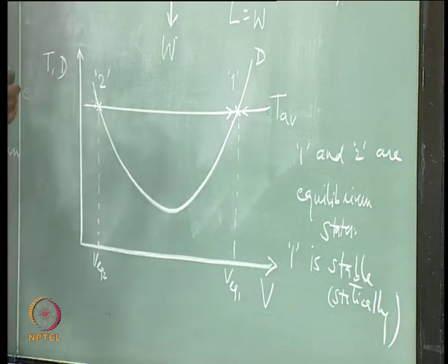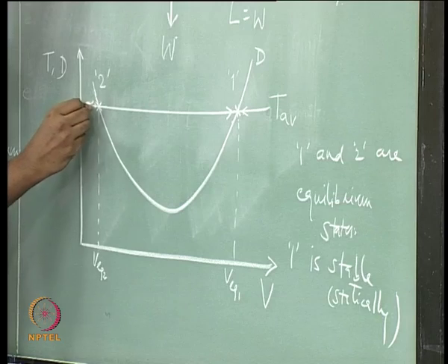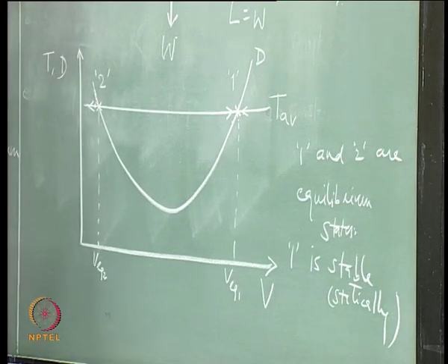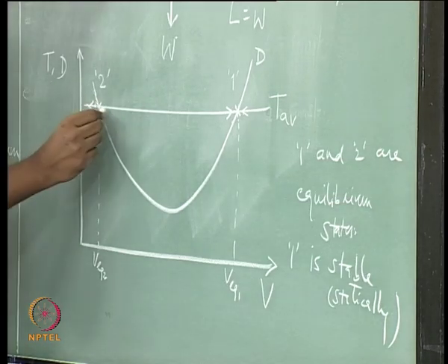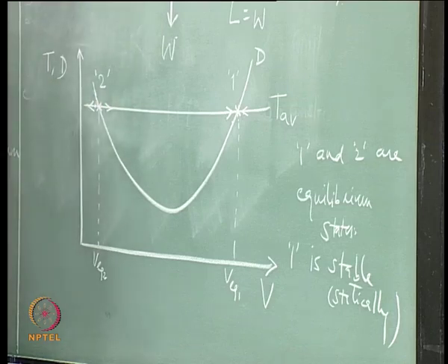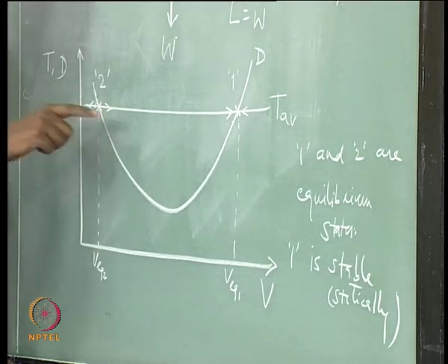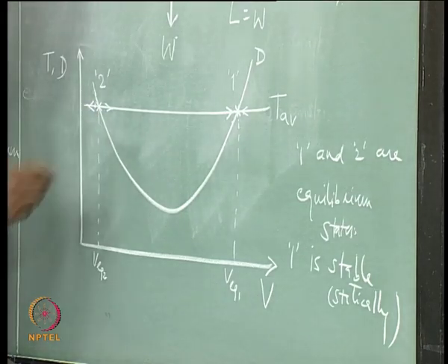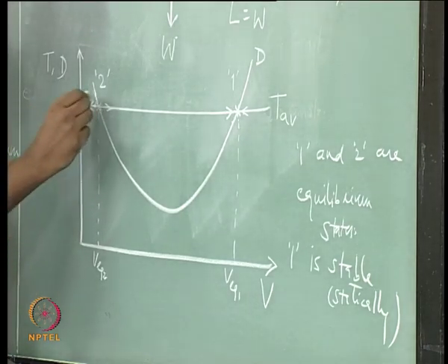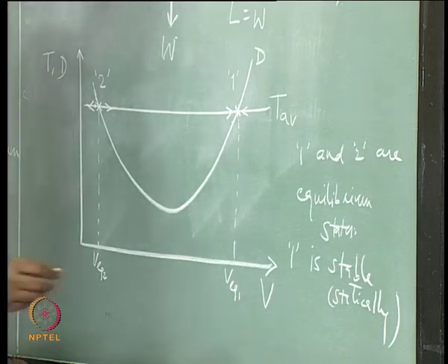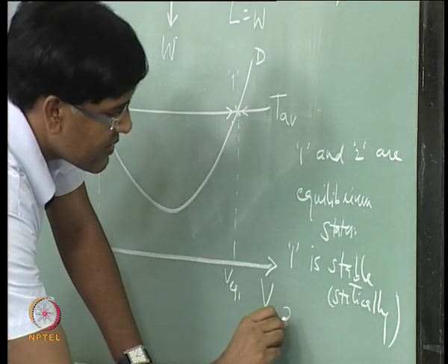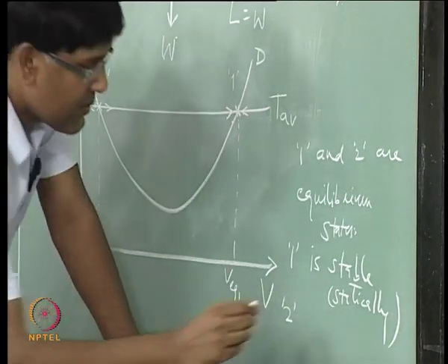So, aircraft will decelerate. So, it is going to take it away from this equilibrium condition, and on the other side, giving the similar argument, the aircraft is going to go away from this equilibrium condition. So, this equilibrium condition is statically unstable with respect to the change in speed due to the disturbance.